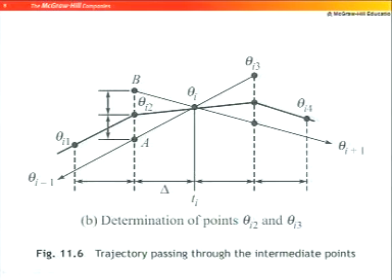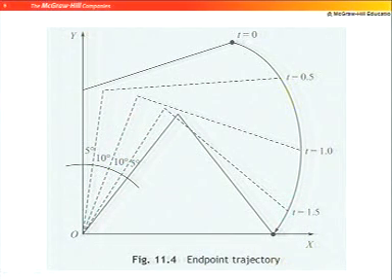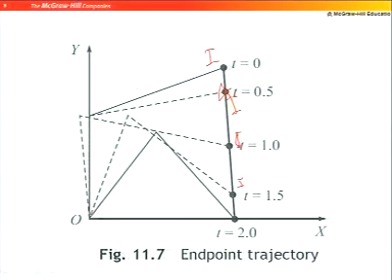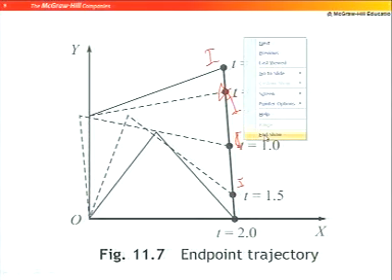But in the previous case, you have done only one inverse kinematics here, and another inverse kinematics here, and the rest of the motions you have done in the joint space. So, only 2 inverse kinematics for joint trajectory planning, and here if you do the Cartesian trajectory planning you have to do it 5 times, but sometimes the application demands this kind of trajectory planning. So, we have to perform inverse kinematics 5 times.